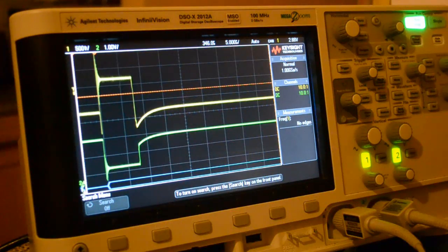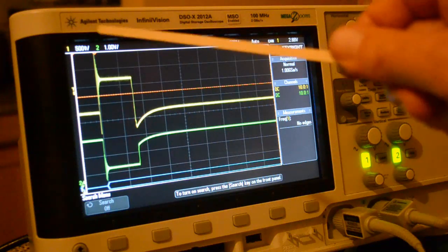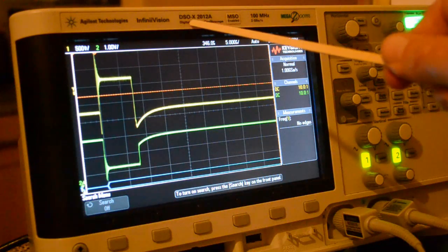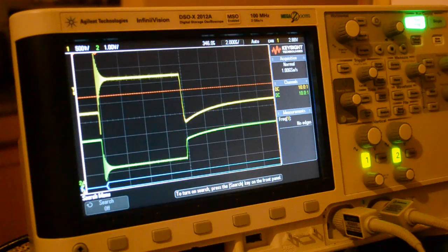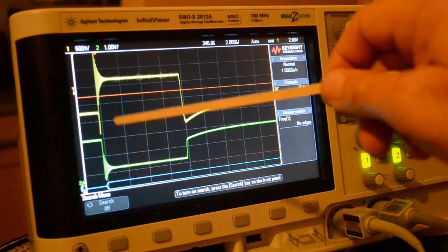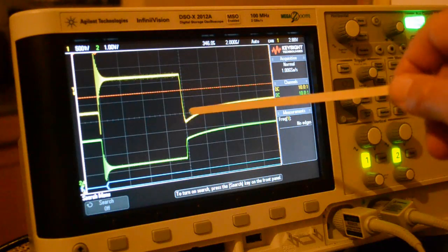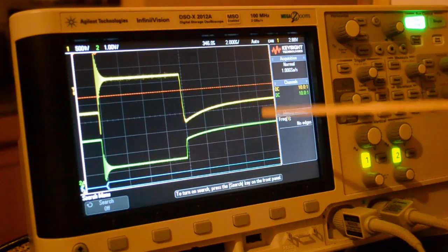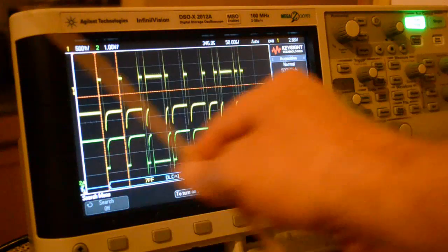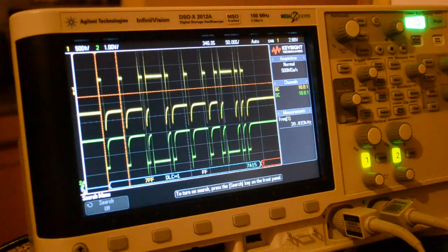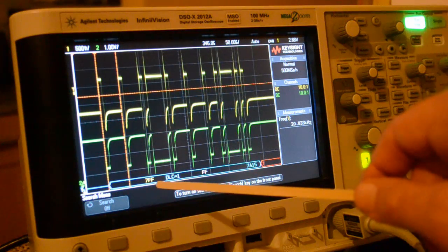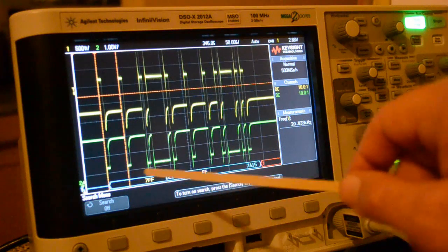So in case you're wondering, this is a Keysight oscilloscope, Keysight Technologies, formerly Agilent Technologies. It's the InfiniiVision DSOX2012A, but I've purchased the serial decode licenses. While I'm on this screenshot, this is CAN high in yellow and CAN low in green. So if I now pull in one whole sequence, remember I said the ID we're looking for is 7FF, which is our decimal 2047 I sent. So that's the correct identification.